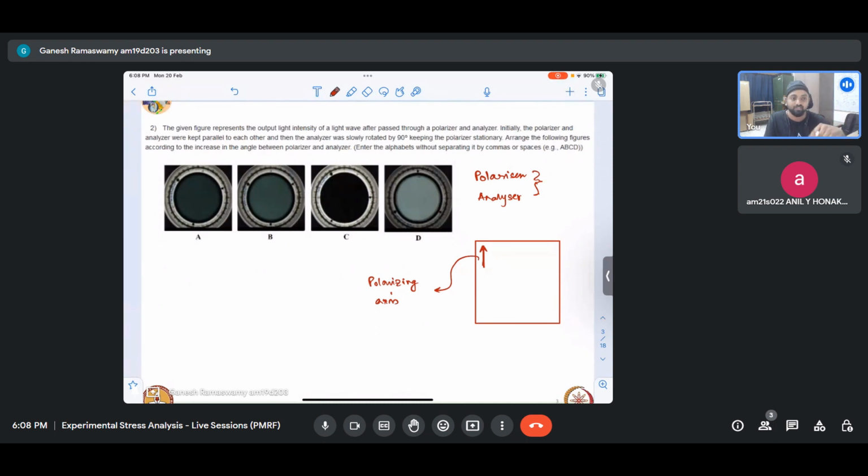In photoelasticity, at least in transmission photoelasticity, we measure the light intensity and directly calibrate it to the stress patterns instead of going through the other route. So essentially, light becomes our sensor. We should know how to control it in order to clearly demarcate the difference in the light that has been brought about by the model behavior under study.